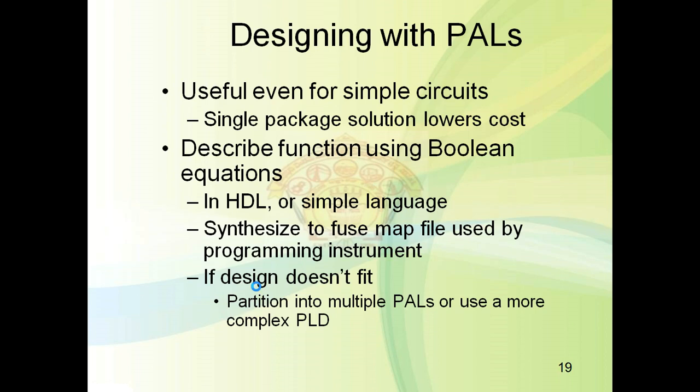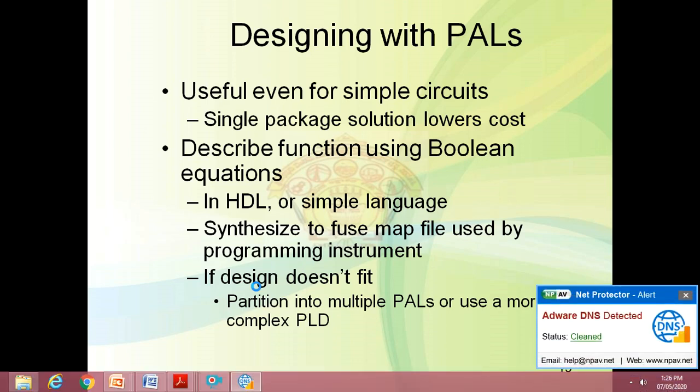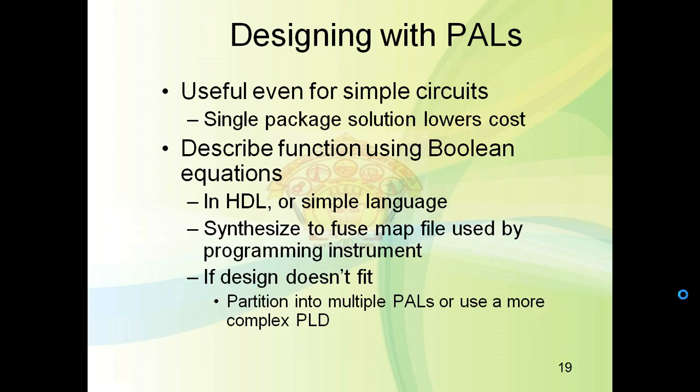Finally the CAD design tool transforms the gate level into a fuse map, and a special programming instrument is used that converts which fuses are to be blown.